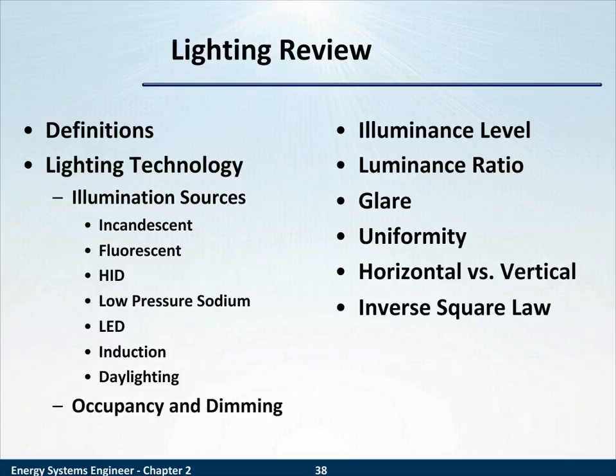Again, these concepts are presented not because you're going to be a lighting designer if you're not now, but because if you're going to be involved in the conversation with your lighting designer, you need to know illuminance level, luminance ratio, glare, uniformity, why horizontal versus vertical surfaces are different, and why when you double the distance, you bring the light at a surface down by a factor of 4.